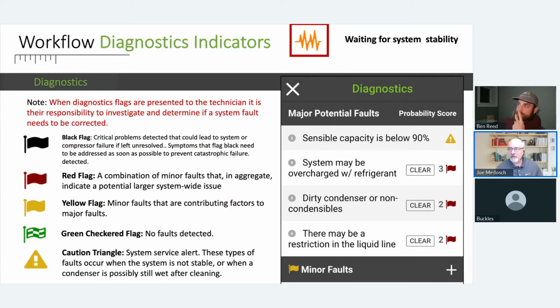Sure. So the discharge probe is on the discharge line. The challenge for that is that you need to take off the cover or sometimes pull the unit apart, and then it goes within a few inches of where the discharge line is. Usually it's not that long, and that's where it's placed. We don't require it unless you have a heat pump, where everything actually gets rerouted, the liquid line or the suction line becomes a vapor line. So it's a little more complicated as a heating system, but it goes on the discharge line, and it's not usually accessible without taking off the cover, if that helped.